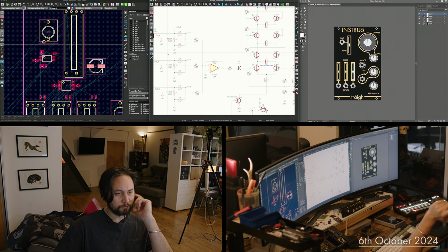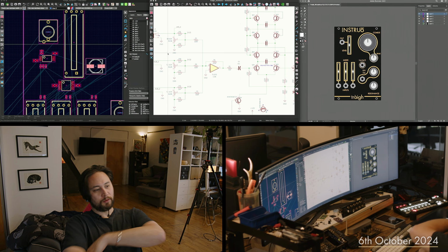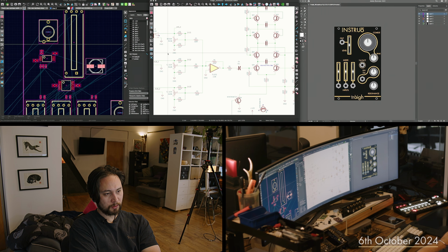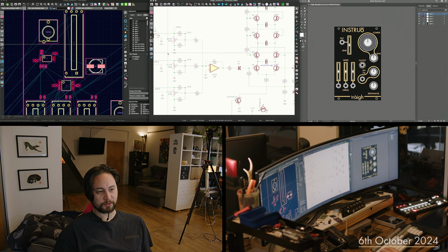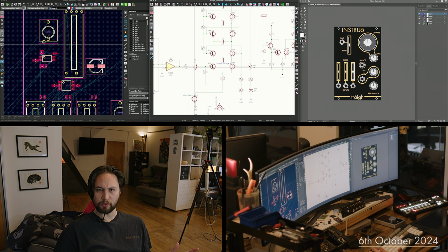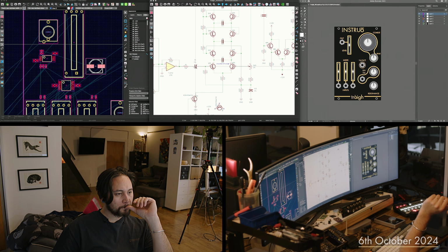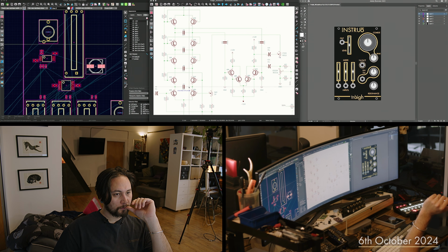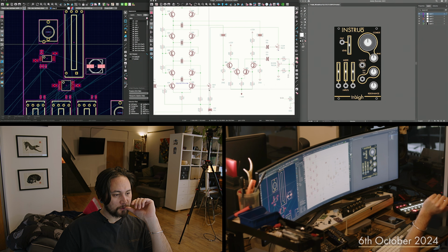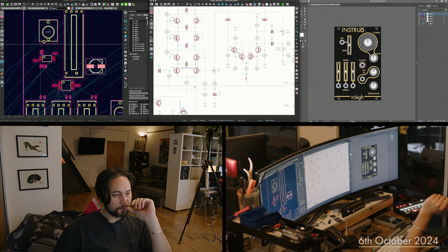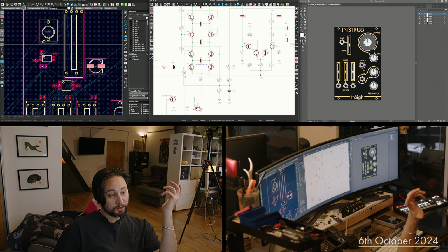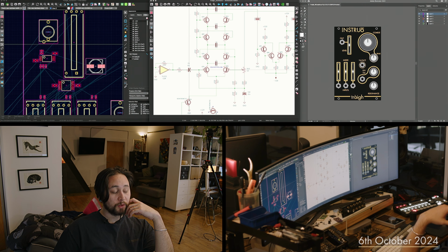Because these are bipolar signals and they're summing together, so it's going to be largely a bipolar signal summed together of different bipolar amplitudes, which means that arguably that should be a non-polarized 10u cap. Kind of the same with a lot of these. I mean, it works fine on the tri as it is. I wonder if it's just low enough amplitudes that it's not an issue with it being polarized.